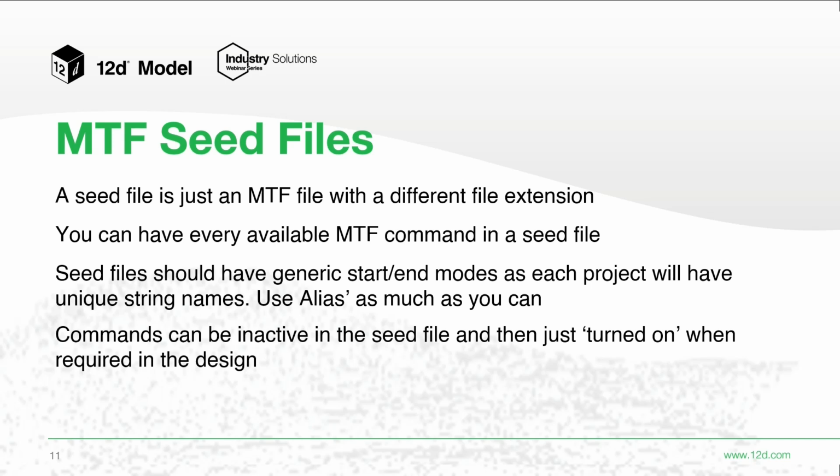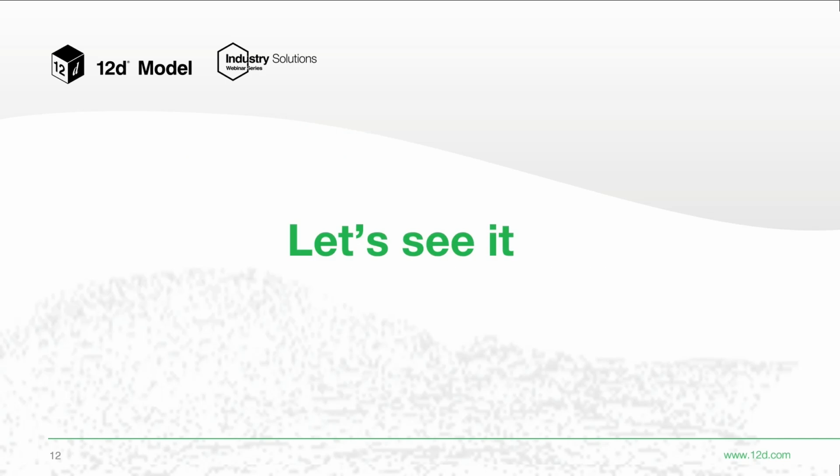So you can have inactive commands. You could potentially have a seed file that does everything you might possibly want it to do in a road situation. It could be inserting your car parks, your driveway cut downs, your driveway entrances, and they can just be disabled within the seed file, so you only need to turn them on when you want to apply that car park or that curb return or that pavement driveway intersection. So yes, seed files, you'll use them everywhere you can, even outside the quick start functionality. So let's go and see it in action.